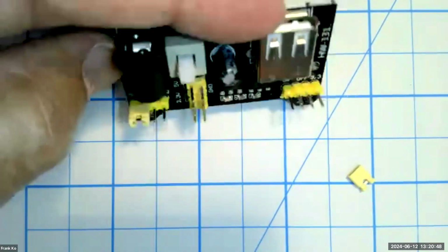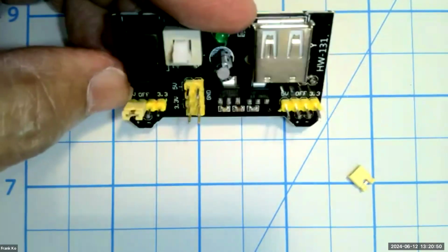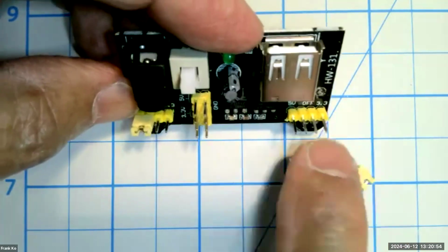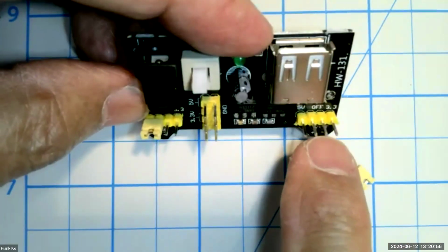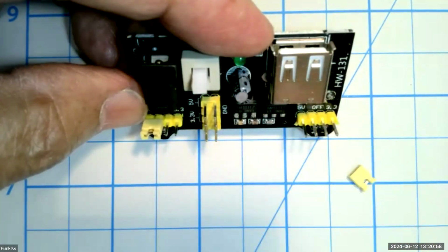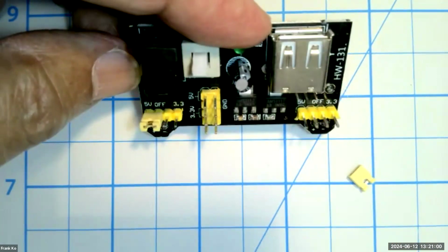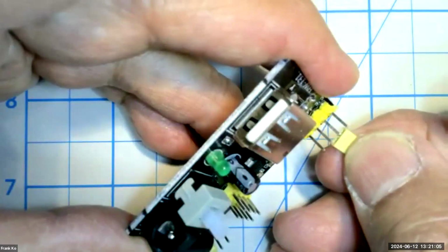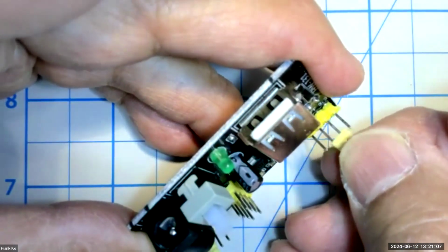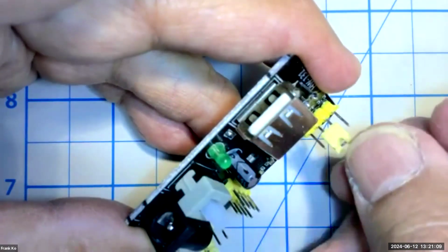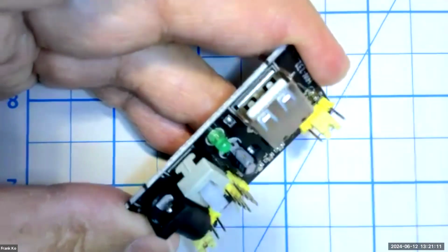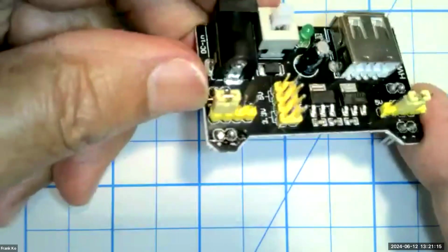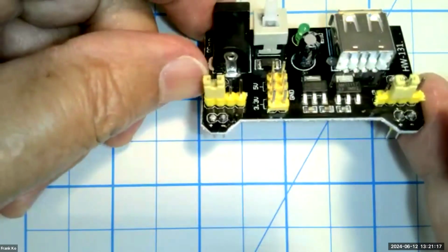Okay. The other side, I'm going to recommend for now, not using 5 volts or 3.3, but connecting the jumper between the two middle pins, which will turn off any kind of power from this side whatsoever. So I'm going to go ahead and do that now. Take this and align, look carefully, and push down firmly like that. Now it's in place. This power supply is now ready to go onto your board.